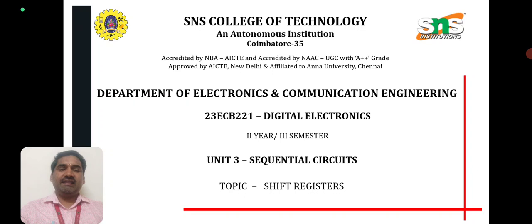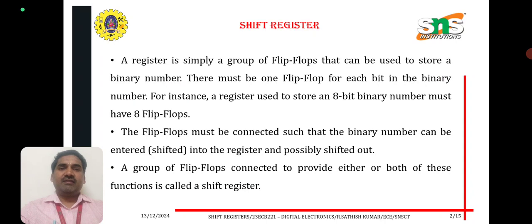Now let us see another video lecture series on sequential circuits, that is nothing but shift registers. First, what is meant by a register? A register is simply a group of flip-flops that can be used to store a binary number. There must be one flip-flop for each bit in the binary number. A register used to store an 8-bit binary number must have 8 flip-flops.